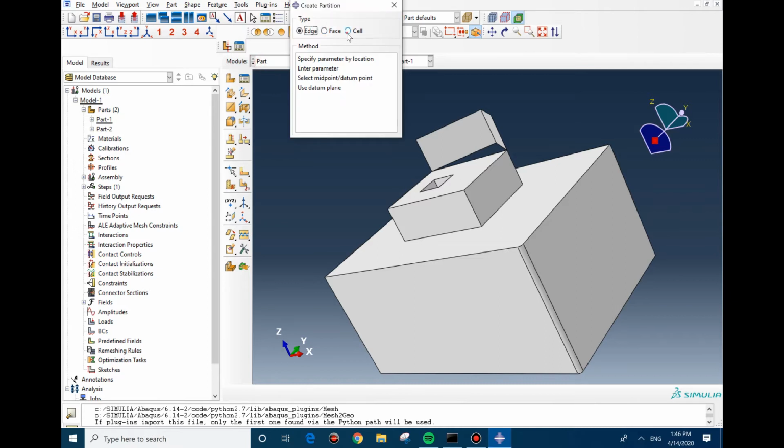For example, for partition, if I click on it, I would prefer to always go with two options. One of them is this one, cutting the plane surface, and then selecting point and normal, and then click on here, and then a line, and then you can see it cut into the half. Okay, but the other one is creating a face.